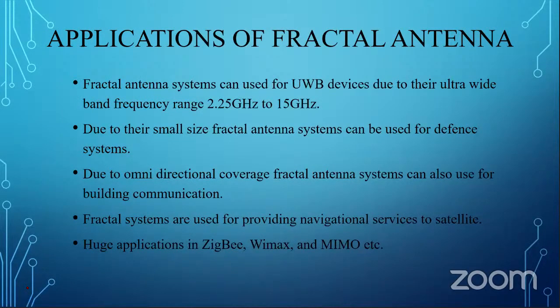And as the last applications of the fractal antenna system, fractal antenna systems can be used for ultra wideband devices due to their ultra wideband frequency range from 2.25 gigahertz to 15 gigahertz. Second point is that due to their small size, fractal antenna systems can be used for defense systems. Third point is that due to omnidirectional coverage, fractal antenna systems can be used for building communication. The fourth point is fractal systems are used for providing navigational services to satellites. Fifth point is the huge application in Zigbee, WiMAX, and MIMO, etc.